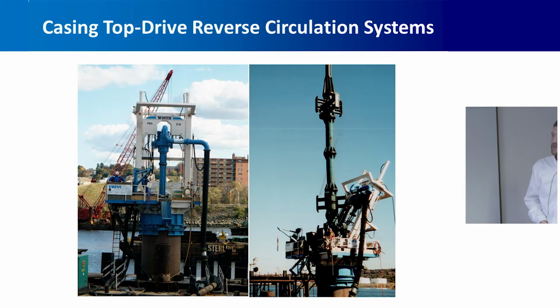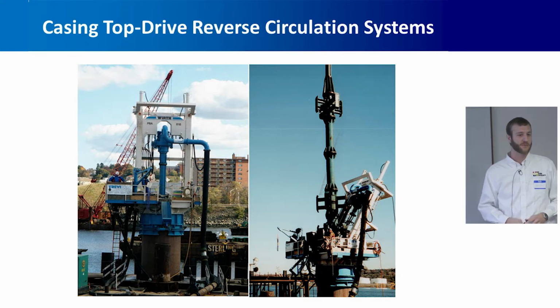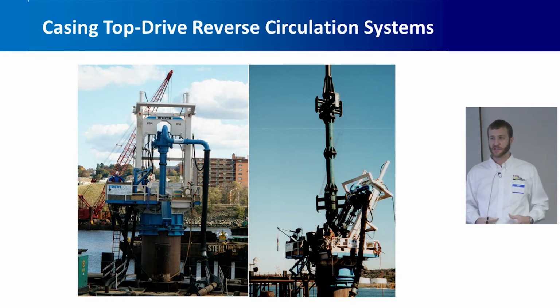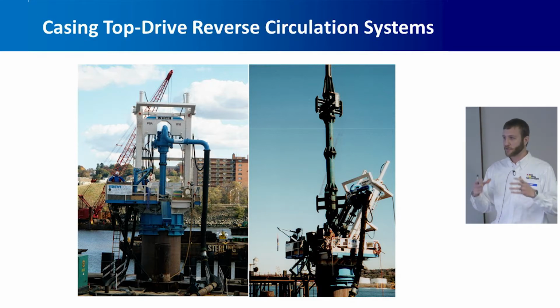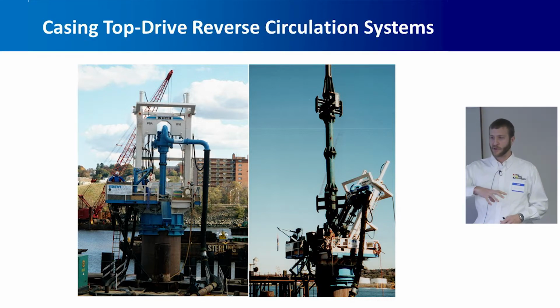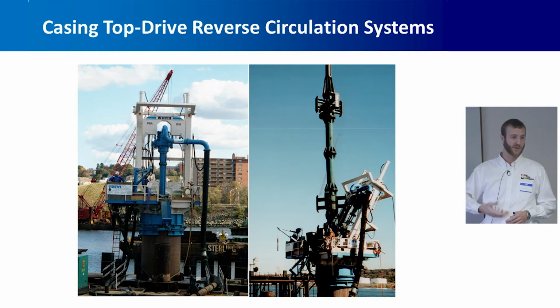Another kind of specialty method is what we call top drive reverse circulation drilling. If you're familiar with a tunnel boring machine, this is kind of like a small tunnel boring machine on its vertical. It's got a full face cutter, which we'll see some pictures of in a minute. It's basically used for rock drilling most often, and it's constantly circulating drilling fluid and cleaning the cutting face as it advances, and it's cutting, like I say, a full face of the rock.